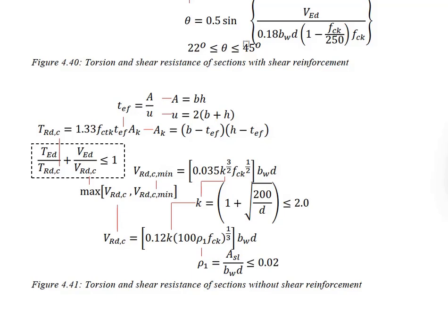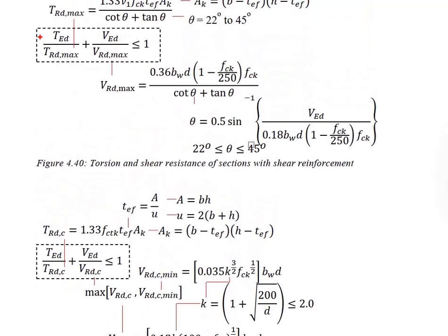When the large cross-sectional area has sufficient shear resistance, no reinforcement is required. For example, we are referring to the slab, staircase, or load-bearing walls.